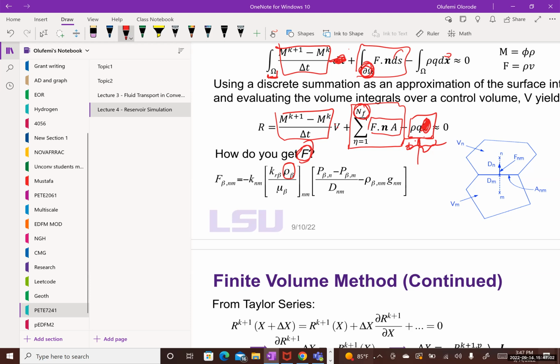And that's where the Newtonian iterations come into play. So Newton-Raphson linearizes the nonlinear equation for you. That's what I just described. This inner loop is linearizing it. And then you can solve it for the change, and then add the change to the previous pressure. And then you keep adding it until you have tested that you have converged. And we'll talk about convergence tests. After you converge, then you have the final answer for P. You've taken multiple delta P's. And then you find the final value for P at that current time step. Then you go to the next time step.